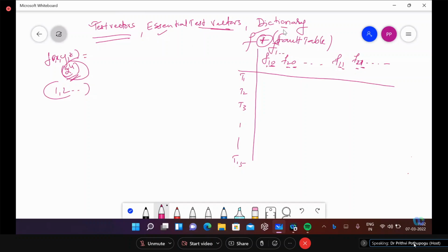And the dictionary will give you the combination of those essential test vectors, defining for that line what is the response of the design if it is faulty. Okay. And the dictionary is just giving you information regarding what will be the probable response of the design when a specific test is applied. Okay, that is some ready reference sort of thing.